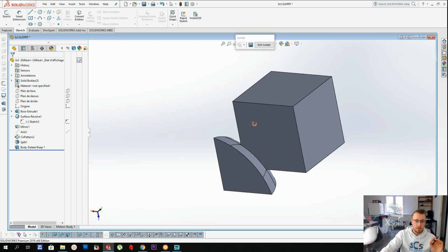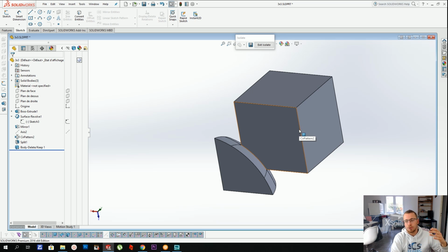As for SLS, for simple puzzles like that, you do not need tolerances at all. The puzzle will adjust itself, and it will be really well printed, so you don't need to worry too much about functional tolerances. Functional tolerances are more useful for SLS when you're using V mechanisms and stuff like that, and hooks where 2 parts grinding against each other might make them lock up or just block or fuse, which is not a good thing.